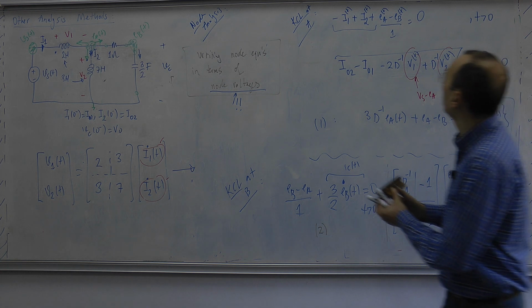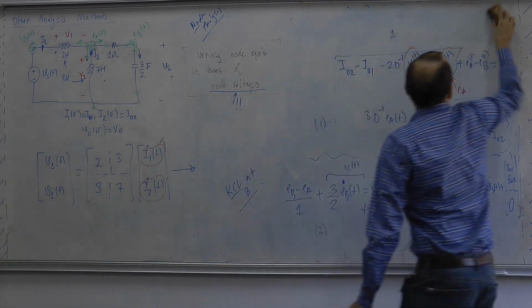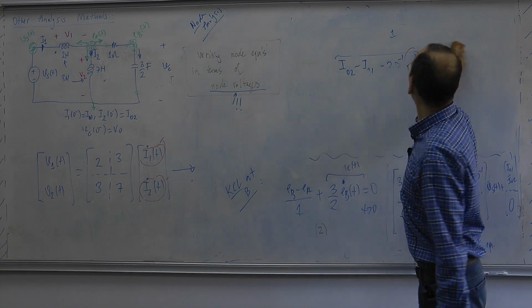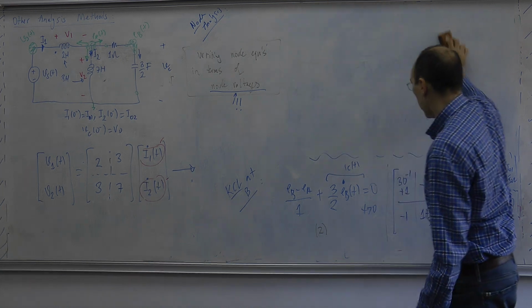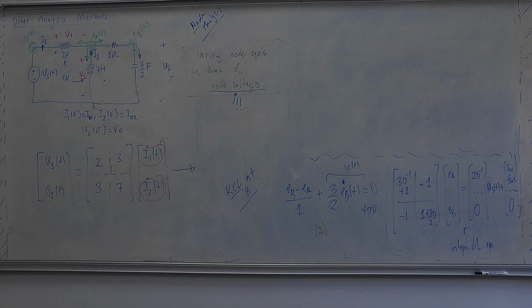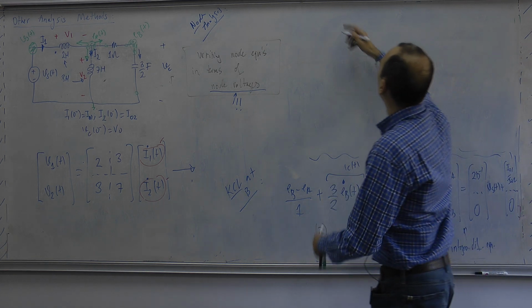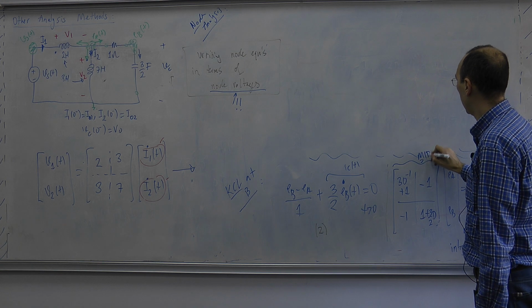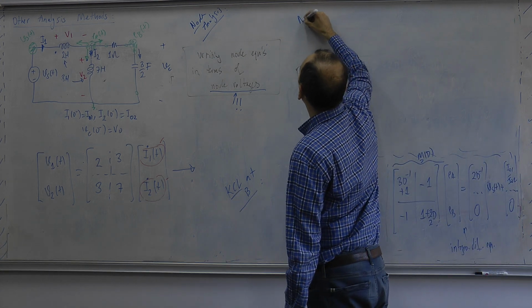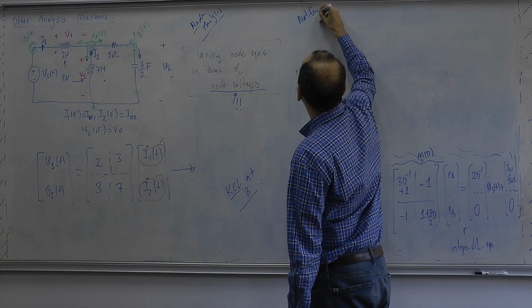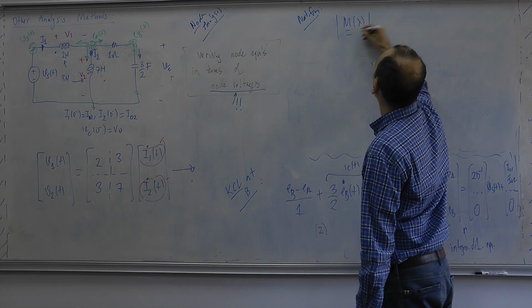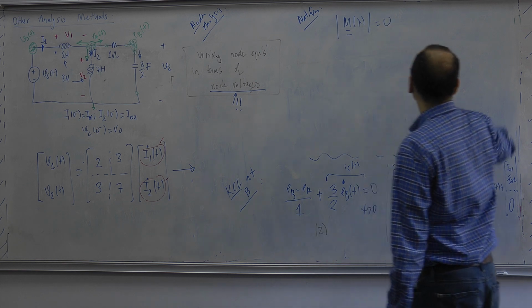Well, we can give it a try. You may miss a natural frequency if it is present at lambda equal to 0, because we have the handicap of, as you see, this integral term. Okay. So again, let me call this, for the sake of simplicity, M of D. Okay. So let me say natural frequency calculation. Natural frequency. M of lambda determinant should be equal to 0.